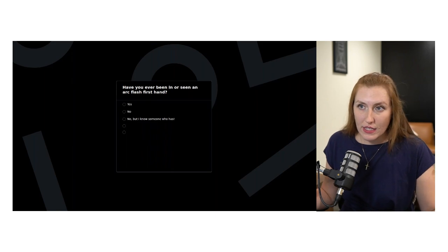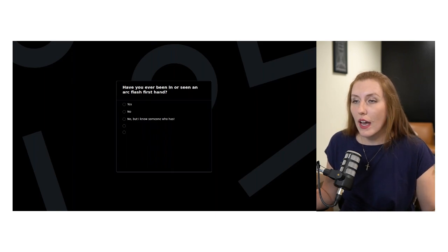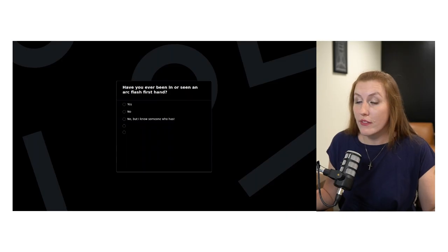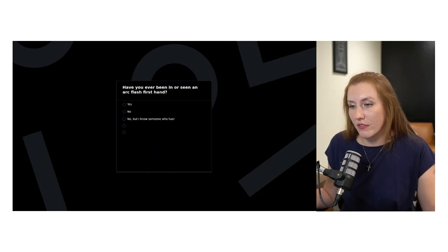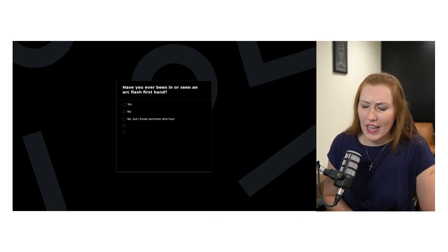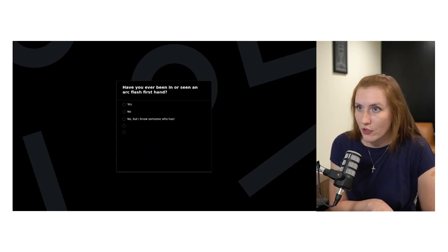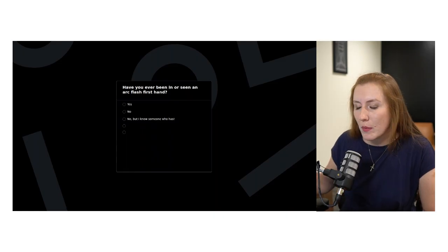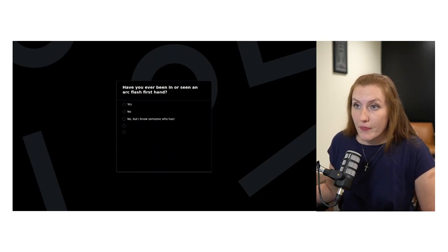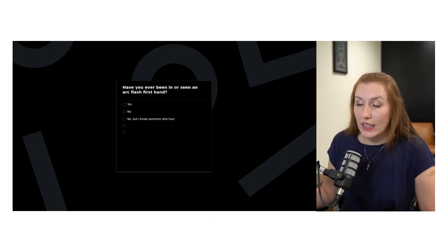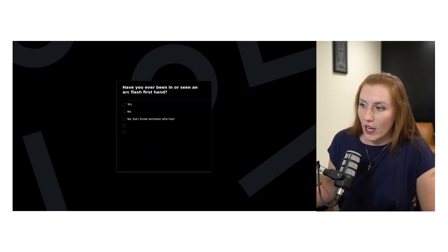It says that it needs the date that the assessment was completed. Depending on how auditors or safety professionals or your own safety program interprets the use of that, there could be a justification for replacing the labels even if nothing changed. Although, as it stands today, and as the 70E is written, which the National Electrical Code points to, remember? It just says reviewed for accuracy, and if there's a change, replace the labels, update the labels. So, long story short, yes, every 5 years, you're going to need to at least review that study and all its details, and then update anything that has changed.